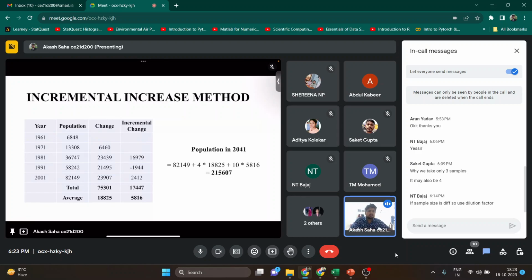Suppose we are trying to calculate the wastewater flow. Now this wastewater flow will not be equal throughout the day. Sometimes it will be high, sometimes it will be less based on your usage. But we want our system to be robust so that it can work throughout. So what we will do, we will take the average flow and, based on our population or our experience, we will multiply it with some peak factor so that if suddenly more flow comes, our system is stable.